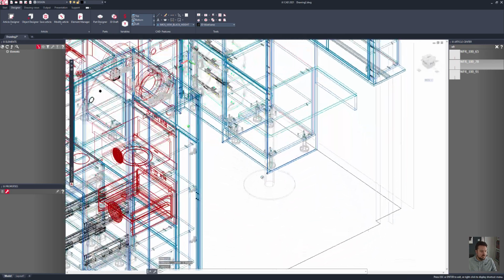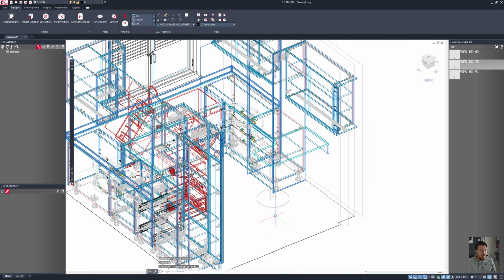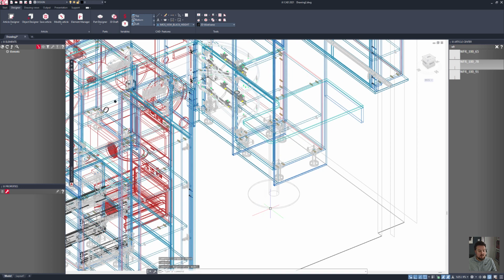And that's just not that tall, so I need to move that down or find a different table leg in here. Rather than it being a table, it needs to be a breakfast bar. So what I'll do is move all of this down. If I use a DI command for distance, I can measure that I need to move this down 170 millimeters.